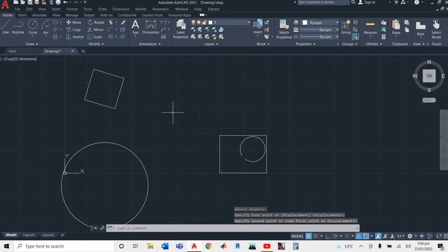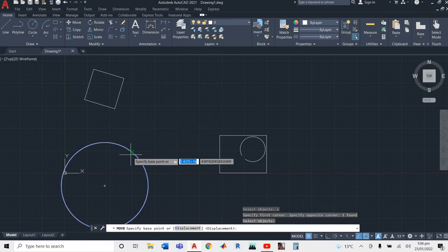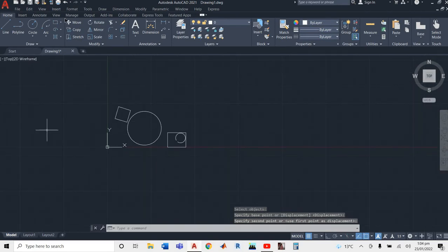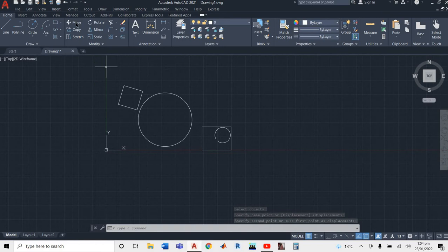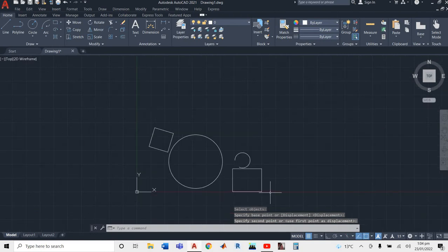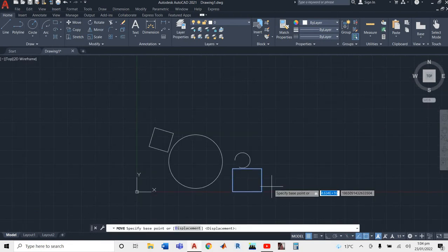If you want to move and copy the object also, MC. Now select. So it's another option I will tell you. Then it's all about the move. For example, we have to move this object. Click and right click in here. Or for example, this option, move.